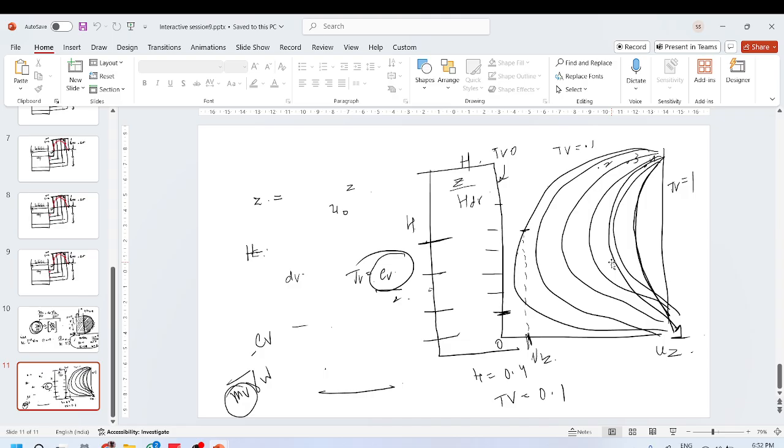And it is not only about the flow that is taking place through the soil, you also need this because when you are loading clays, if you have a clay strata, you need to know what the excess pore water pressure will be over this material and how long it will take to dissipate, or how long it will take for effective strength to regain, because that is what you need when you are building foundations even, isn't it?